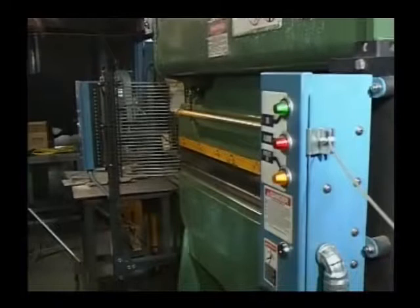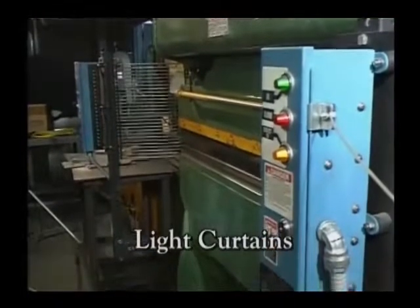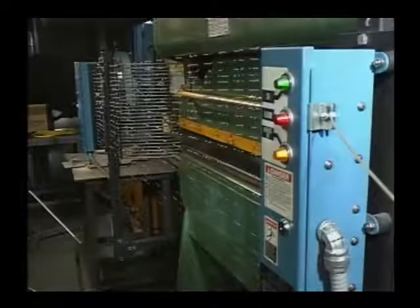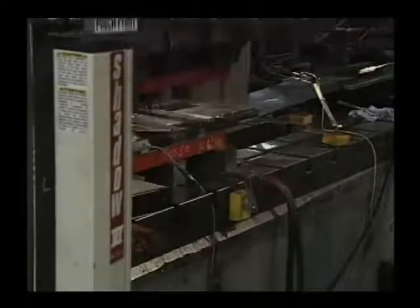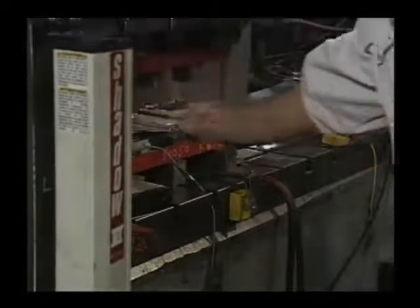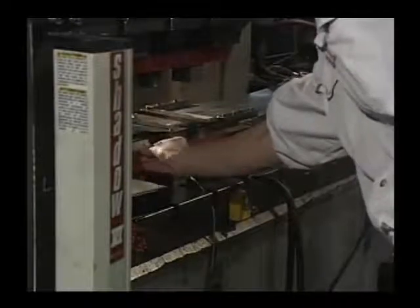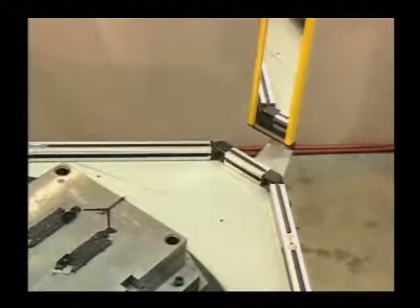Light curtains are one of the most common safety devices in use today. These photoelectric systems use beams of fluorescent or infrared light to create invisible barriers around machine perimeters and in front of points of operation. If something such as a hand breaks one of these barriers, a relay switch trips the machine's power and it is cut off. This protects the workers by stopping the machine before they can encounter any moving parts.